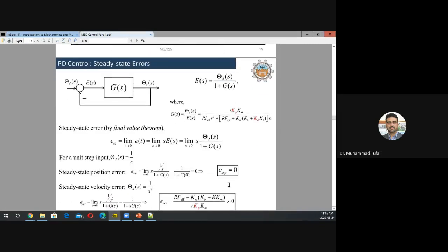So generally, when you have E of s, there is a limit called the final value theorem, with which you can get the steady state error. Just take a limit of this, multiply it with s and make s tend to 0. So it means, bring this expression in place of E of s, and take the limit of s in it, okay. Because in the time domain, whenever we go into Laplace, we go into the s domain, okay.